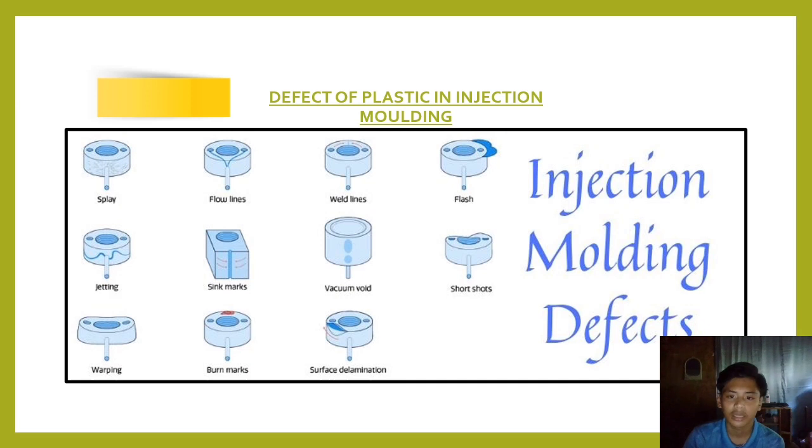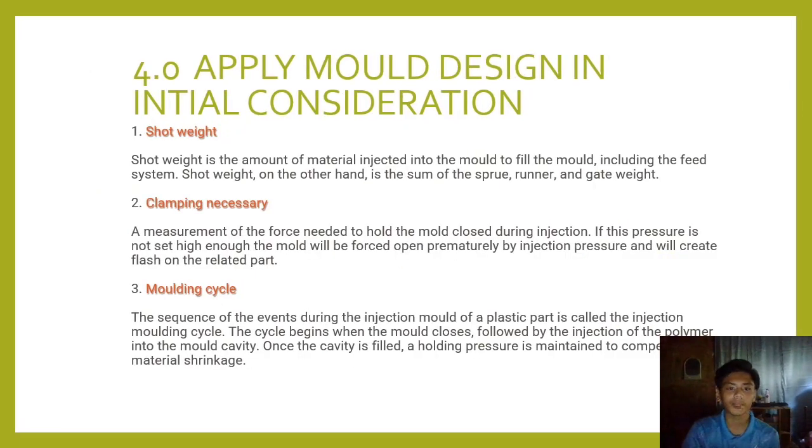There are 10 more defects that I didn't say, which are splay, flow line, weld lines, flash, jetting, vacuum void, short shot, warping, and surface delamination.